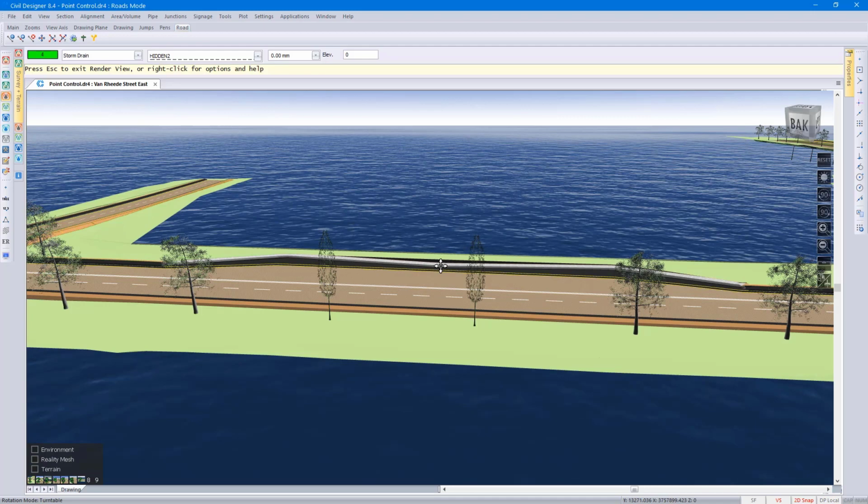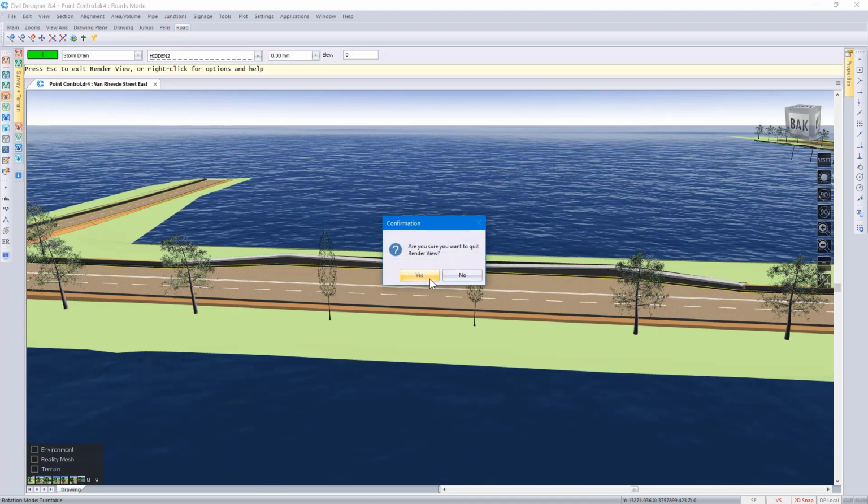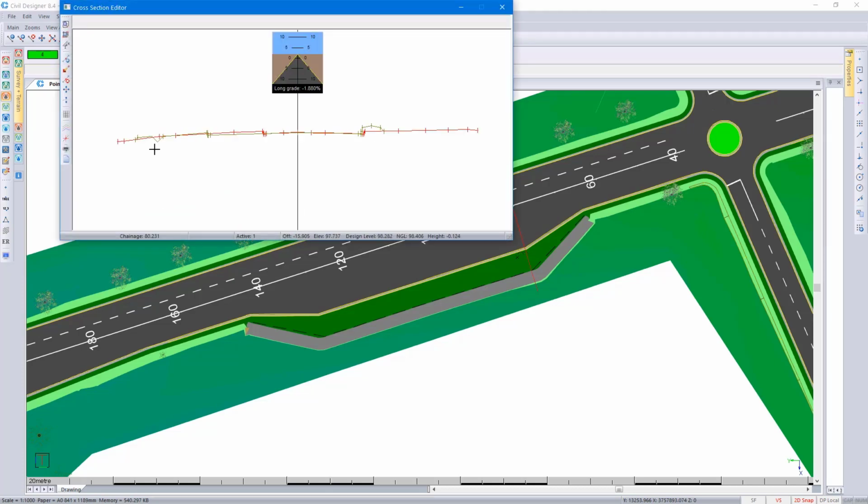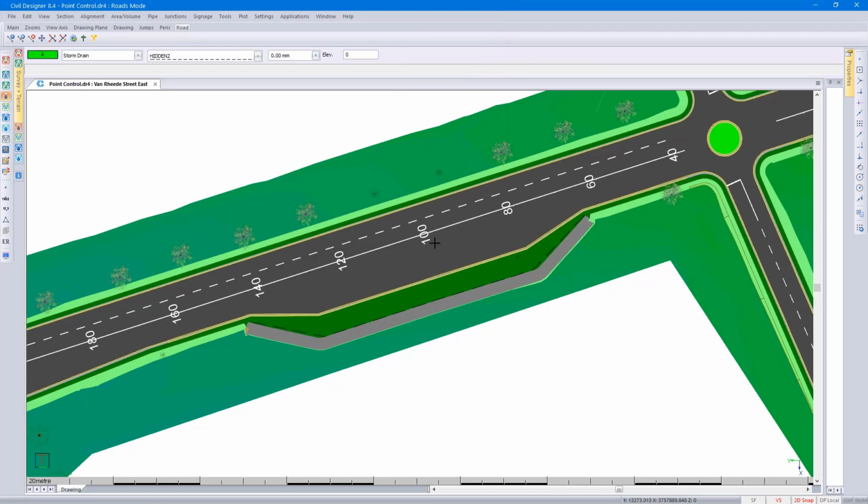If you want to view the V-drain in a cross-sectional format, we then go to Section, Graphical Edit, go and select a point. Looking at the position or the height of my V-drain, if I press page down, you can see the V-drain elevation drop. That being the lowest point, and then moving back up. In this example, I just used a polyline, but you can also go and use a spline. Let's use that as an example.